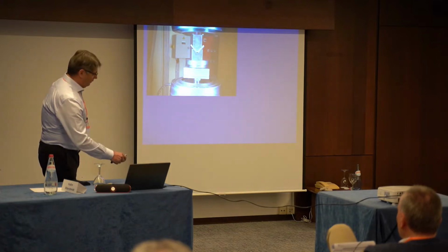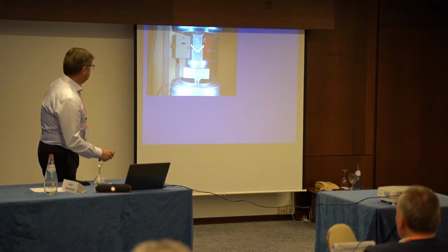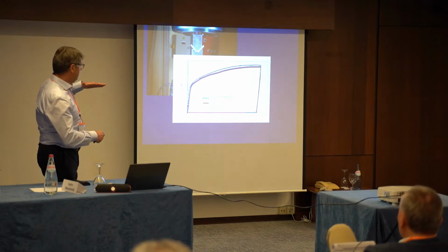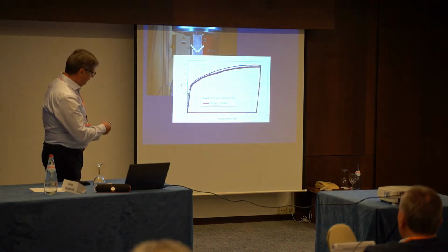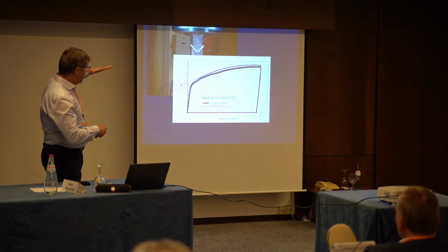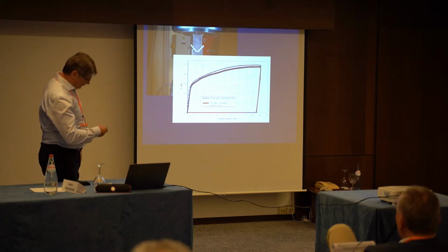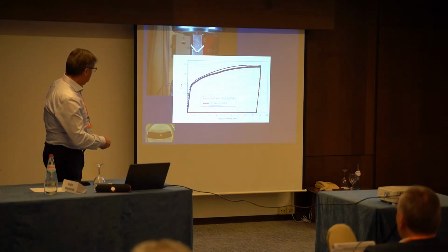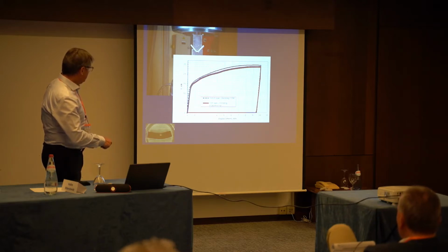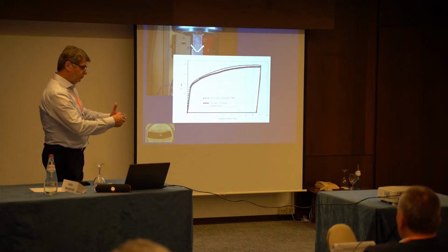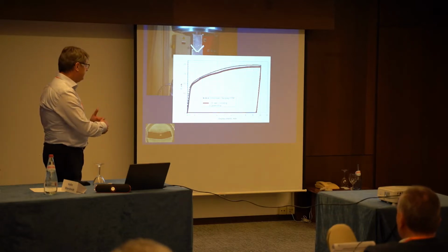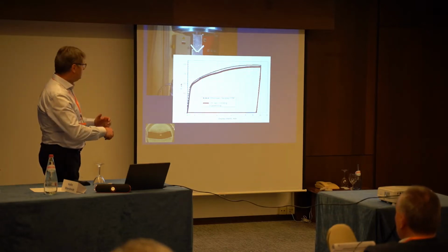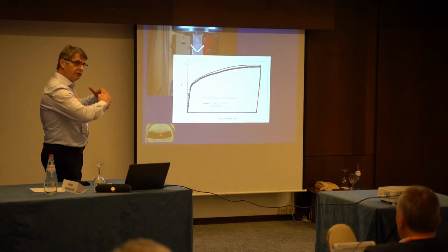Yes, we actually have the three sections with different, let's say, bending. One was with the 5 millimeters depth. Here you can see it for 10 millimeters depth. And now we compare also with our results. We put the model, which we got from the tensile test, in Abaqus, and try to simulate this process of bending.